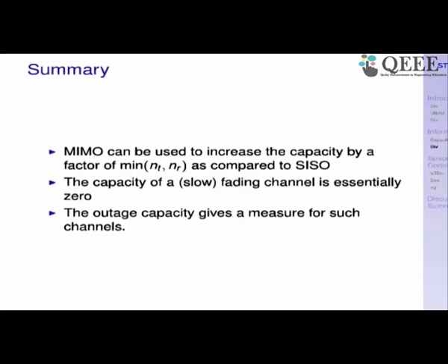We have defined array gain formally, from an SNR perspective. Now, a very short question at this point. I'll ask you to tell me what is the array gain for a MIMO channel? See, remember, we had said that for the SIMO case, the array gain is NR because it is the gain in average SNR as compared to the average SNR.